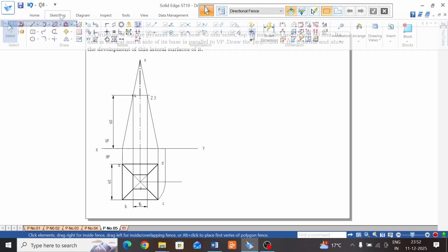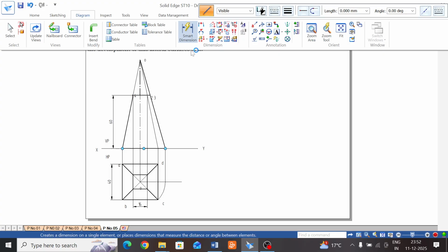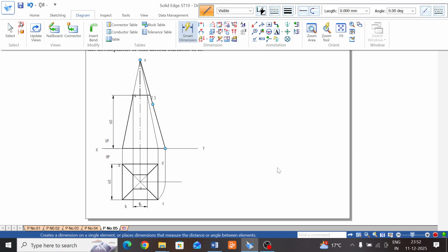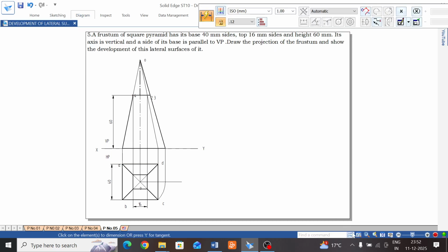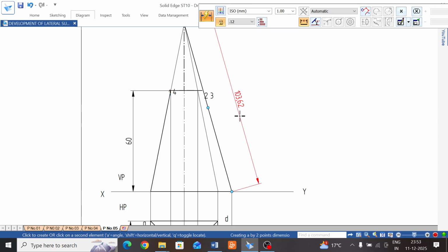And now join those lines by thick line, the outer box, thick line from this end point to the apex end point, single line. Okay, this is the exact end. And from this 2 to 3 to 1, and this bottom portion is the cut portion, the below portion is thick. Now measure the small dimension, this total length using the small dimension. Make use of zoom area.